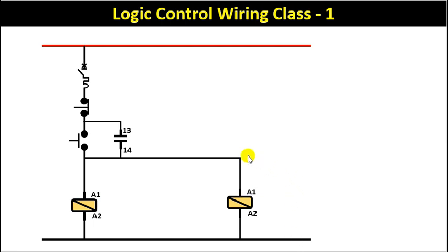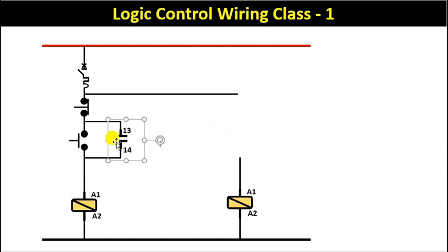So what we have to do here is remove the power supply which we connected here, and connect it to the above terminal of the stop push button. Because after pressing the stop push button, motor B should not turn off. So we connected one wire here. Now the power supply which goes from here will go to this contactor. But to turn it on, we have to use a NO contact. So for motor A, we will use its NO contact. I will copy paste this NO contact here. So now we have one more NO contact. This NO contact is of this contactor. I wrote here A NO. It means the NO contact of motor A is used here.